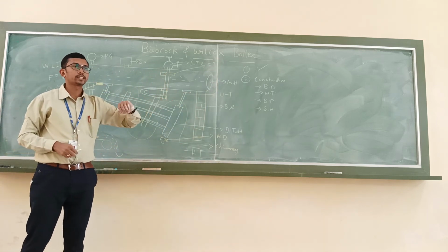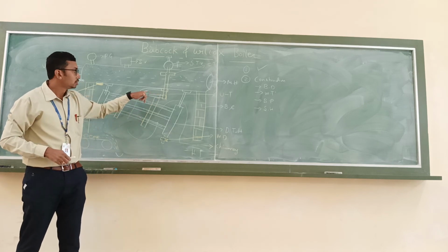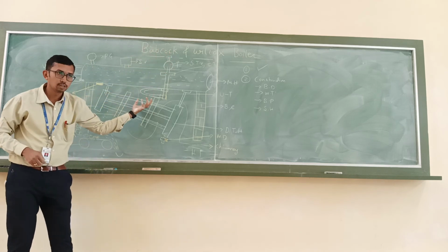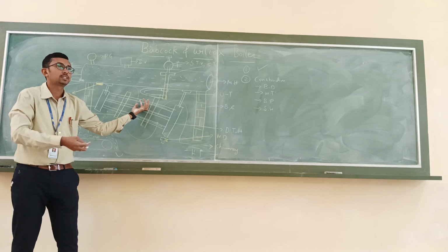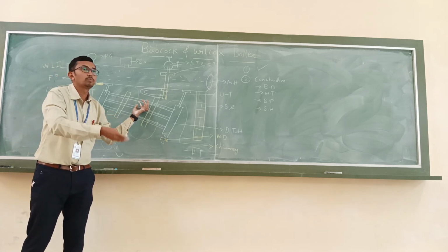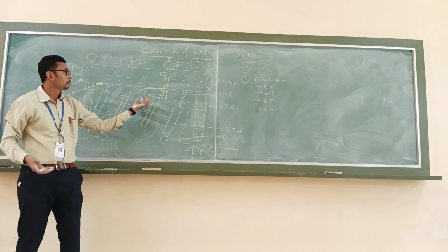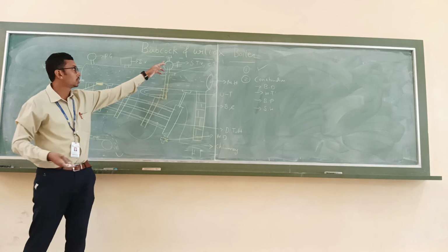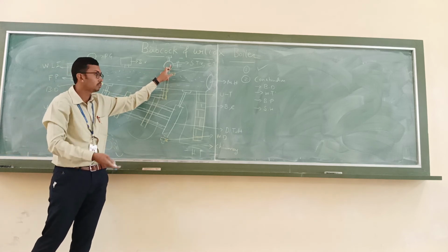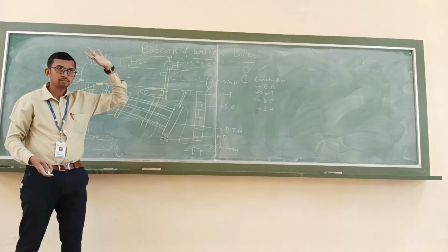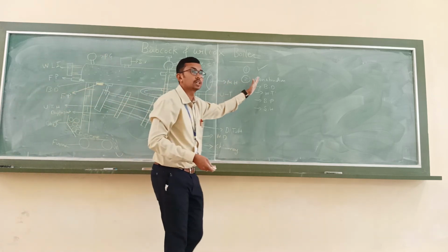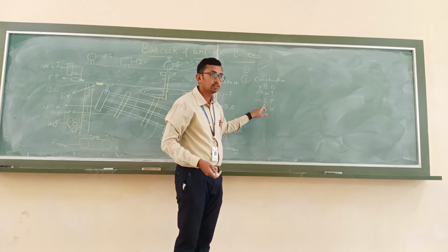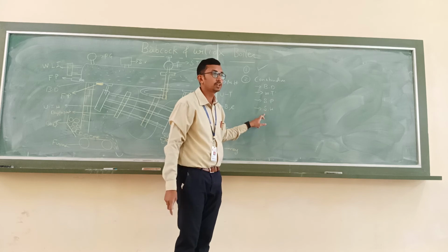So superheater. How are you going to explain the superheater? It is a U-shaped tube. So the wet steam from the T-tube comes to the U-tube, where the wet steam will be converted into superheated steam with the help of hot gases flowing around it, and finally it is circulated to the further application with the help of a steam stop valve. So these are the major constructions. You have to explain the boiler drum, water tubes, next one is baffle plates, and next one is superheater.